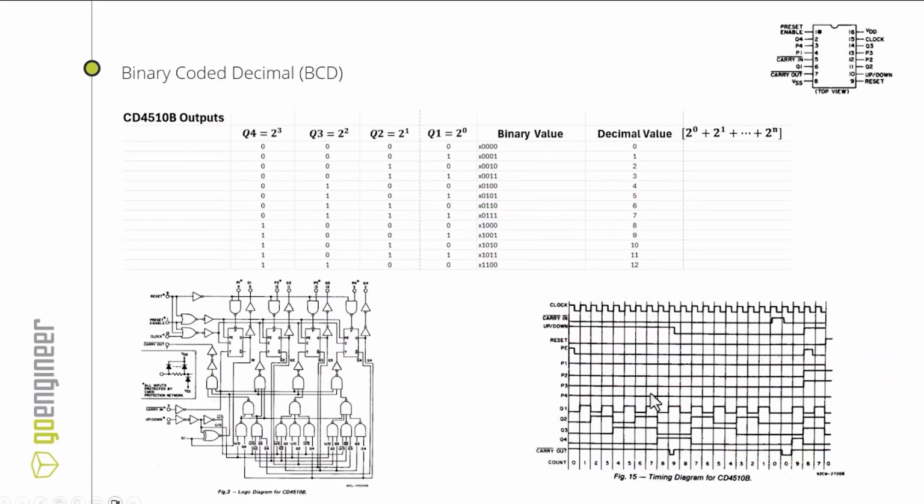And so for the rest of my PSpice simulations, I was validating the outputs of all my CD4510s that I had for my seconds, minutes, and hours. Starting with the seconds, I was making sure that this component would take my 1-second pulse coming from my timer and be able to store its decimal value starting at 0 all the way up to 9 and then resetting.